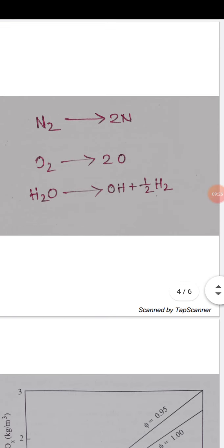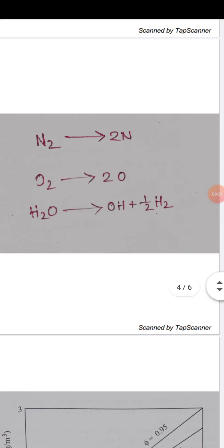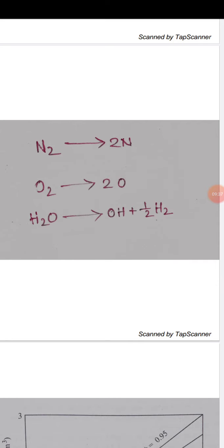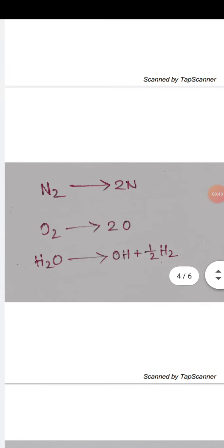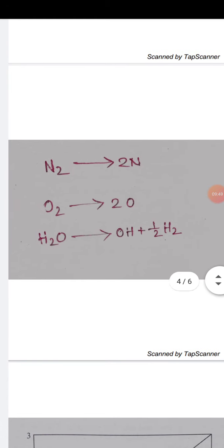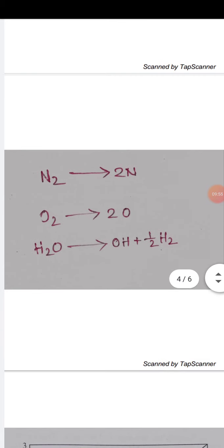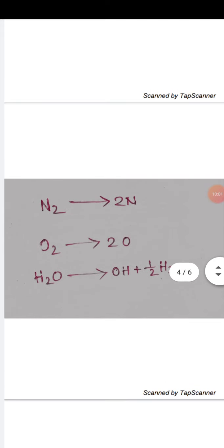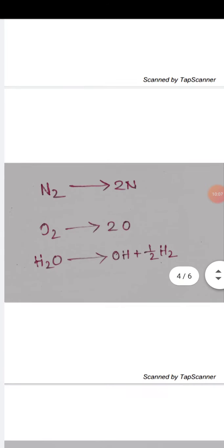If one goes a little deeper into the combustion chemistry, it can be understood that these reactions, from the breakdown of diatomic nitrogen to the breakdown of water, move much further to the right as high combustion chamber temperature is reached, because that does not happen in the low temperature range.